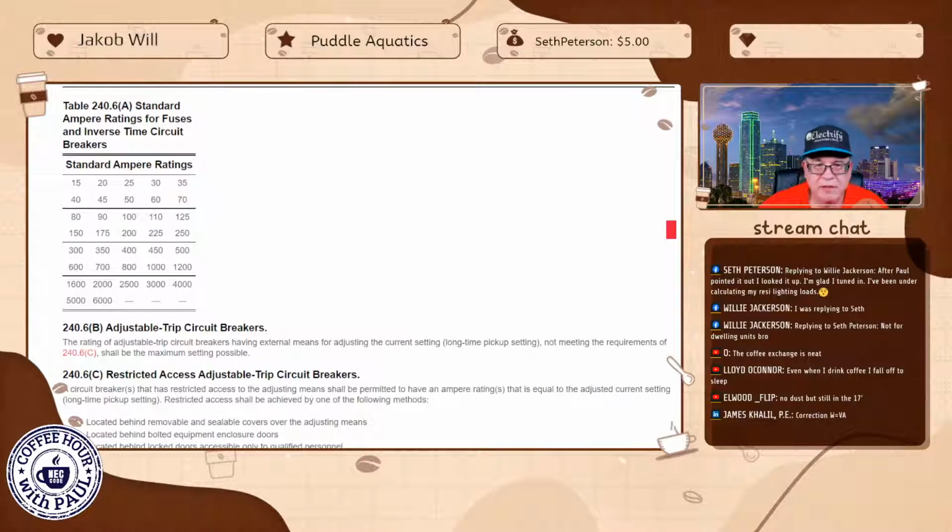It was 152, so it's over 150, so we could put it on a 175 amp rated device. That's a big difference from our 136 based on the heat that we used, the 3 units, because that one was 136, so we would put that on a 150. That can make a difference. You've got to be careful which one you select, because that's the difference between me being on a 150 amp breaker versus a 175. Just to show you how that could take place.